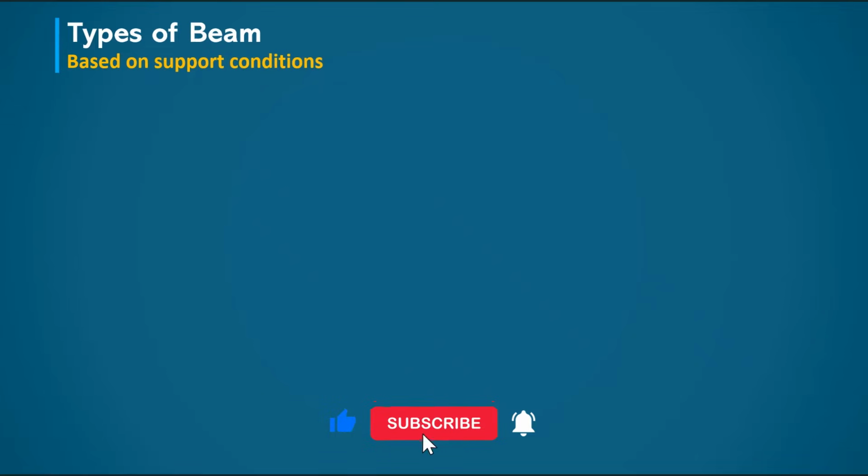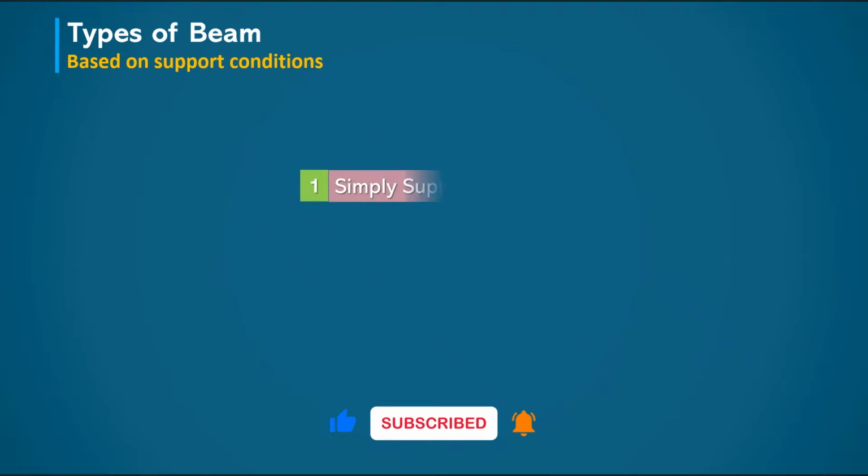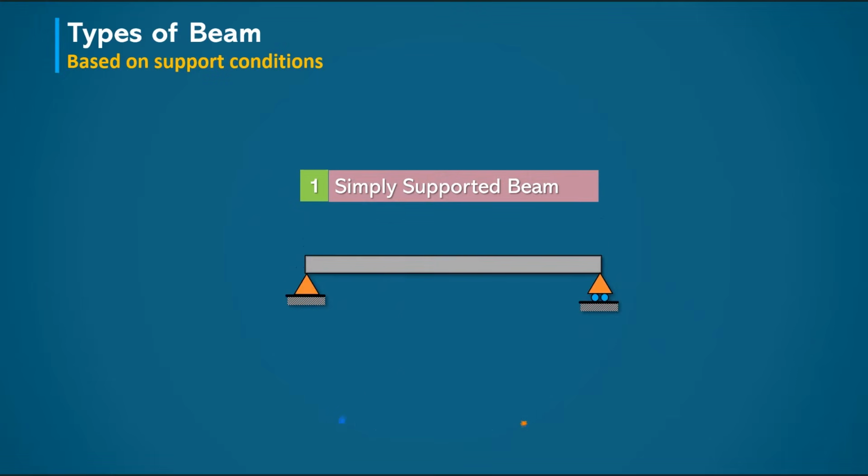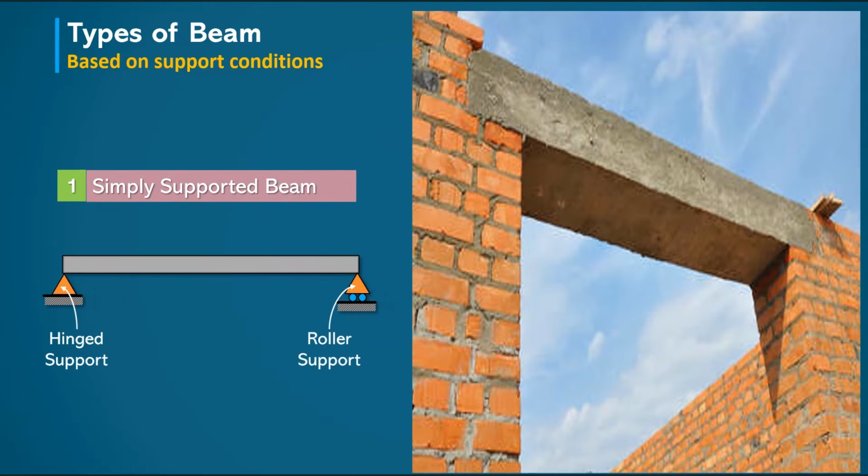Now, let us move to next category, that is types of beams based on support condition. In this, first type is simply supported beam. This type of beam rests on two supports, usually a pin and a roller support. You will generally find this type of beam as a lintel over opening and bridge decks.